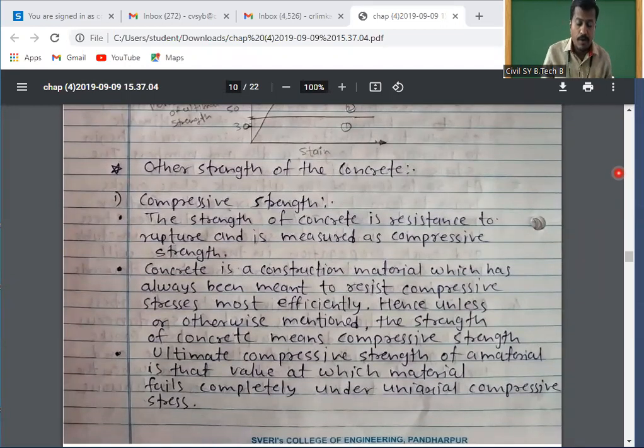Before keeping that, if required, you can give compaction, a slight vibration to the concrete, just to level the surface of that mold. If you have done the compaction correctly, then there is no need. But if you feel that the concrete must get compacted in the concrete cube mold, then you can use the vibrating table. There you can put your concrete cube block on that particular table and vibrate it for just 1 to 2 minutes maximum.